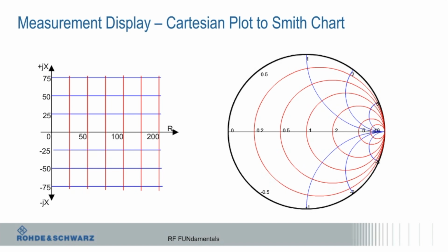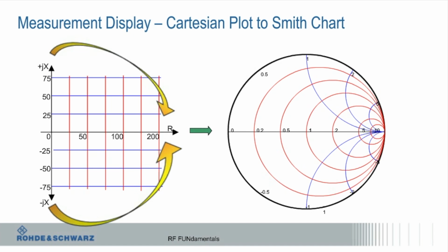Not to say it's not important to everybody, but the reality now is more of the components that you buy are already 50 ohms, so you're not going to have to match them. Historically, with a Smith chart, you'd take an amplifier, for example, and it would give you some points on a Smith chart, and you'd want to get those to 50 ohms to match to whatever your load is, or your input is.